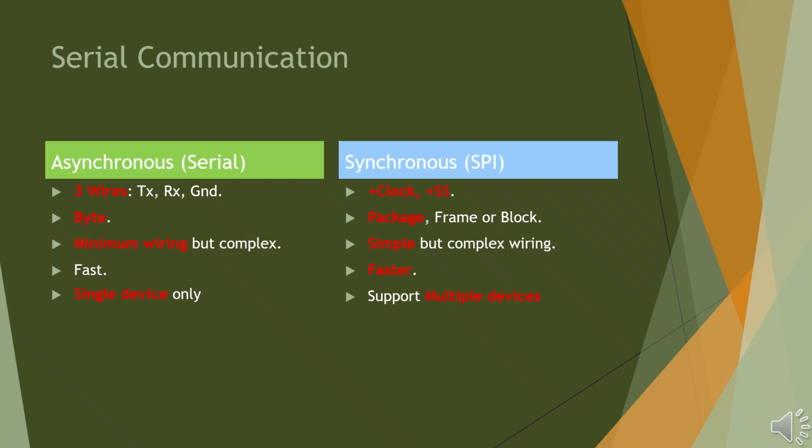Only 3 wires are typically used: TX (transmit), RX (receive), and GND (ground). This simplicity makes asynchronous communication easy to implement and ideal for short, low-speed connections, such as UART, RS-232, and USB to serial adapters. However, because each byte requires start and stop bits and relies on local clocks that may drift slightly, the overall data rate is lower compared to synchronous methods.